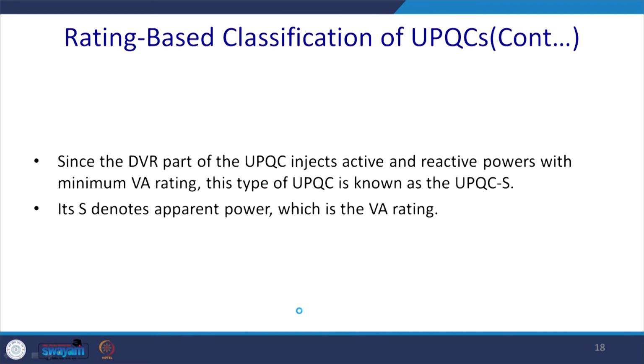And apart from that, since the DVR part of the UPQC injects active and reactive power with a minimum VA rating, this type of UPQC is known as the UPQC-S, where S denotes the apparent power, which is the VA rating optimization, optimized VA rating, that stands for it.